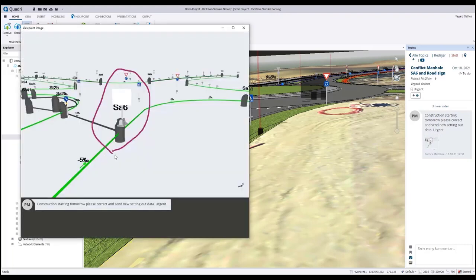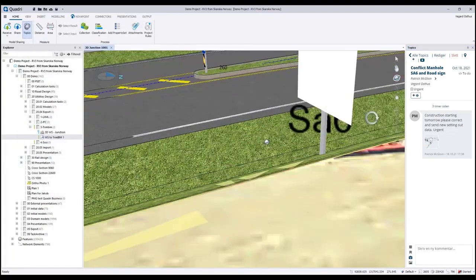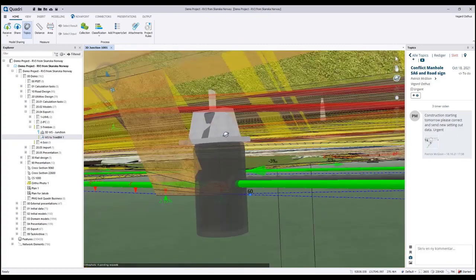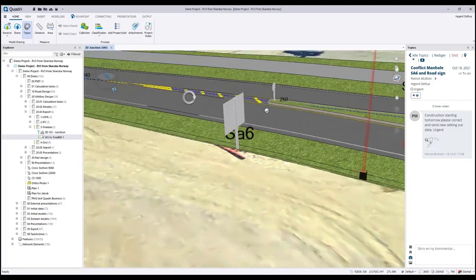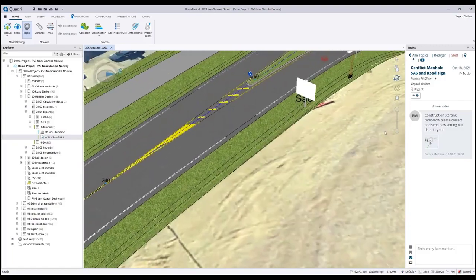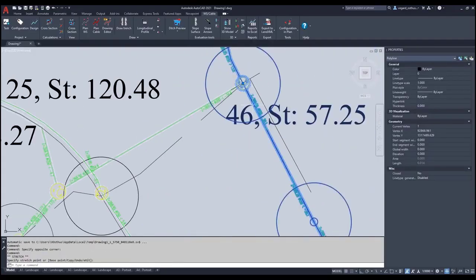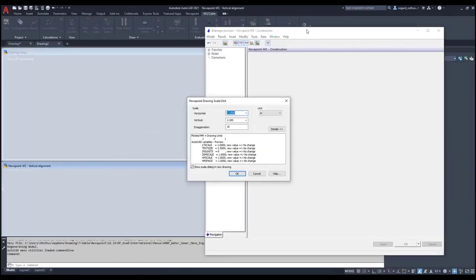Okay, so I can also see what specifically he meant, but I also want to check myself by checking the model and going below. I can easily see the conflict with the concrete. So what I'm going to do now is redesign the road drainage and then recalculate. This is the part where I do the redesign in the NovaPoint water and sewer module.